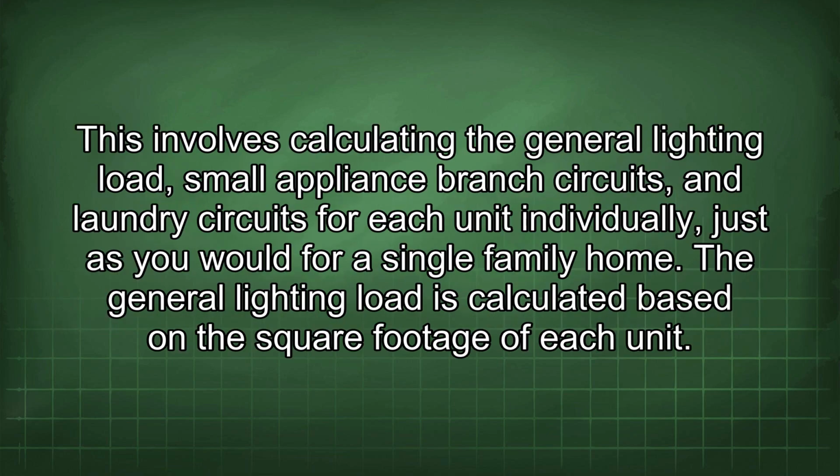Standard calculation for duplex requires treating each unit as a separate dwelling. This involves calculating the general lighting load, small appliance branch circuits, and laundry circuits for each unit individually, just as you would for a single-family home.